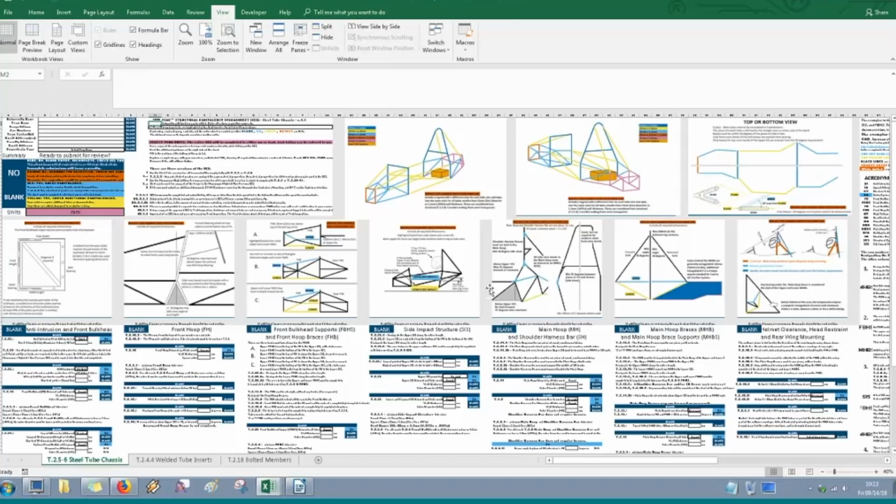This might be a very good place to have experienced students on your team sit down with new members and work together. Always have a copy of the rules open at the same time, or if your team is thinking about moving to monocoque construction, definitely read the SES. It'll help define requirements for your design. And from a structural perspective, it does the same thing for EV cars.